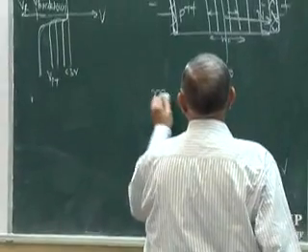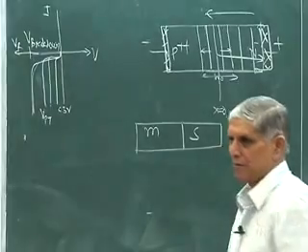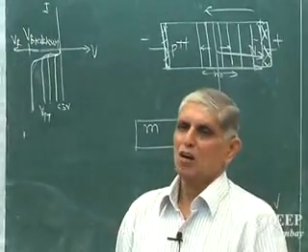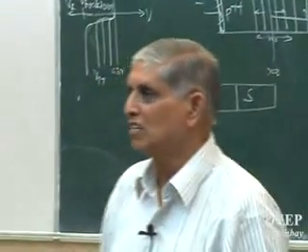You have a metal and you have a semiconductor. Now we know two different materials, if you join, there will be an issue. What is the issue? If the metal work function, a word which I am now going to introduce, is not same as work function of the semiconductor, then something will happen, and will create a barrier.